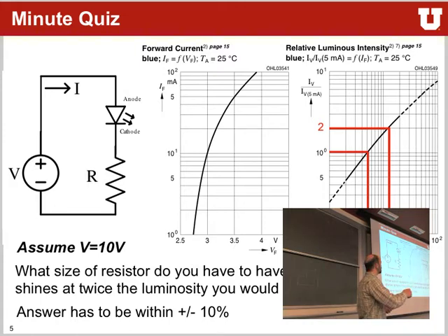Exactly. You need to find the voltage drop corresponding to the 15 milliamps. So if you go here, this is the forward voltage, forward current in milliamps. This is actually not 5, this is 15 here. Go down. So it would be 3.5 volts. Now what?